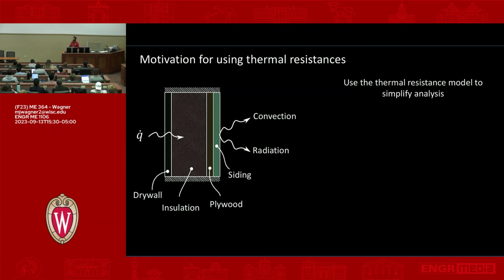When we're teaching more complicated heat transfer problems, particularly in the grad level class that we teach, we always focus on starting with a resistance network or a resistance model because it gives you that intuition of what's going to happen, and then you solve the more complicated problem and check it against the simple model.